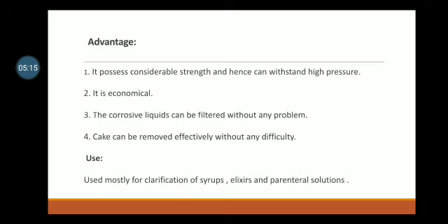Advantage: it possesses considerable strength and hence can withstand high pressure. It is economical. The corrosive liquids can be filtered without any problem. Cake can be removed effectively without any difficulty. Used mostly for clarification of syrups, elixirs and parenteral solutions.